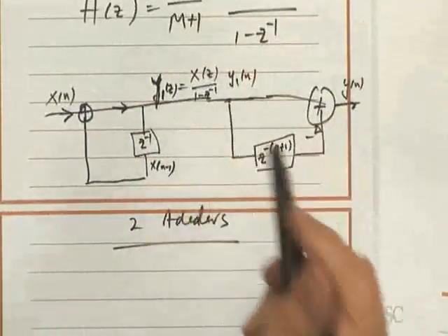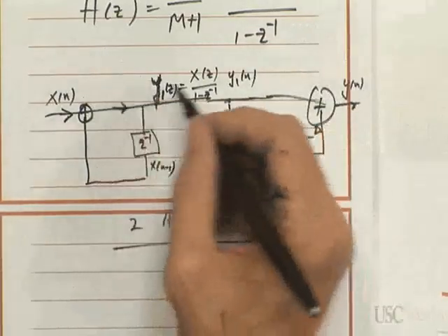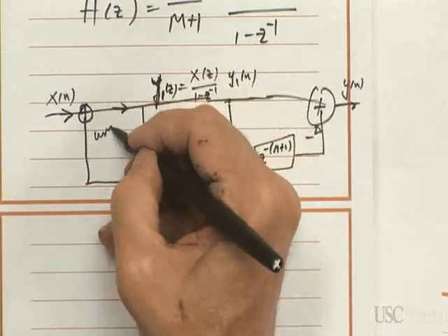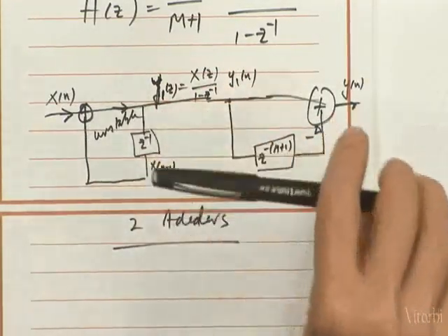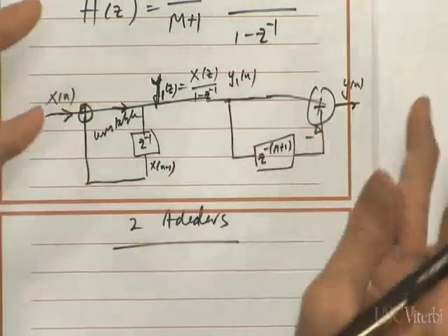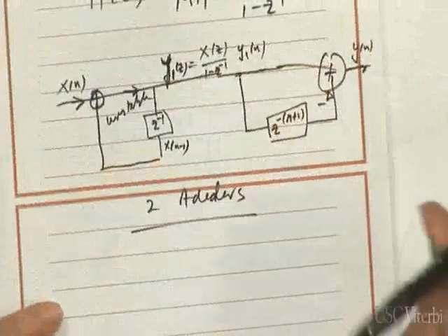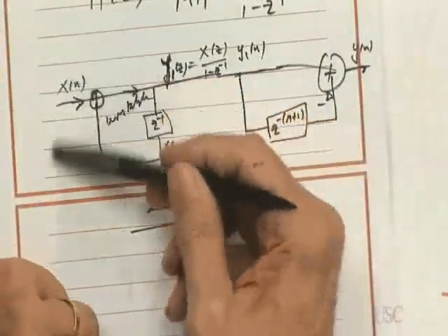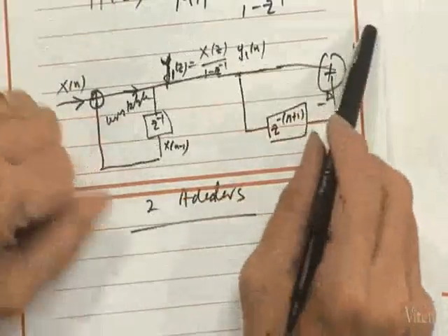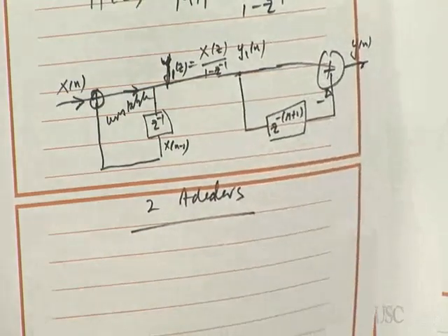Now, the only problem with this is it just violated something I just got done talking about 5 minutes ago. This filter here is unstable, right? This is an unstable filter because it just keeps adding samples over and over again. But it turns out if you implement this with what we call 2's complement arithmetic, I'll touch on this briefly toward the end of the course, then you can actually implement this without introducing overflows or anything. So anyway, it's just kind of an aside, just some interesting little tidbit on implementation.